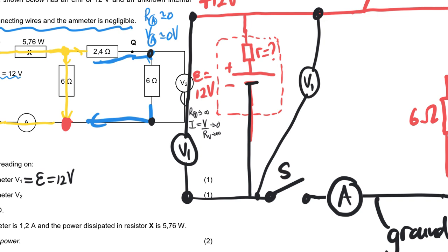Now in practice, in order for it to do that, there needs to be a little leakage current that runs through. So if it's an analog voltmeter, for the little electric motor inside, which moves the coil's needle, there needs to be a little current in order to do that. But we're ignoring that leakage current. So we're assuming no current is flowing. This is just measuring the theoretical volt drop across the battery.